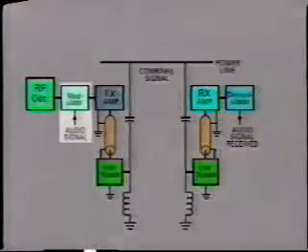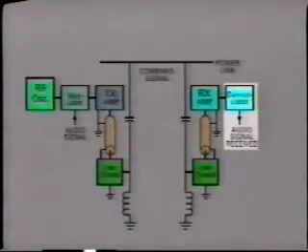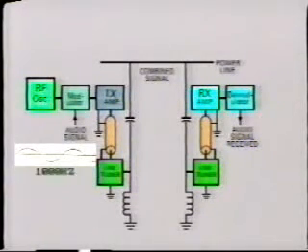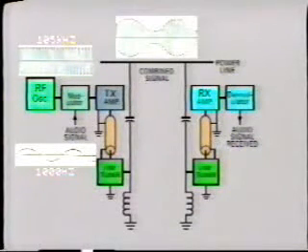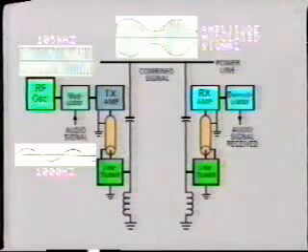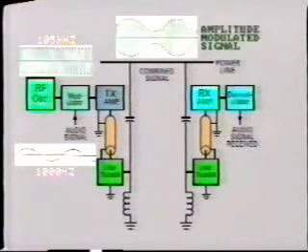This audio signal is mixed with the RF carrier signal in a modulator before transmission down the line. The mixed signal is then demodulated in the receiver at the other end, leaving only the audio signal. Suppose, for example, we wish to transmit a constant 1,000 hertz signal, perhaps for alarm purposes. This audio signal is superimposed on the high-frequency carrier signal, say 105 kilohertz, and modifies the amplitude of its wave. This is known logically as amplitude modulation, AM.